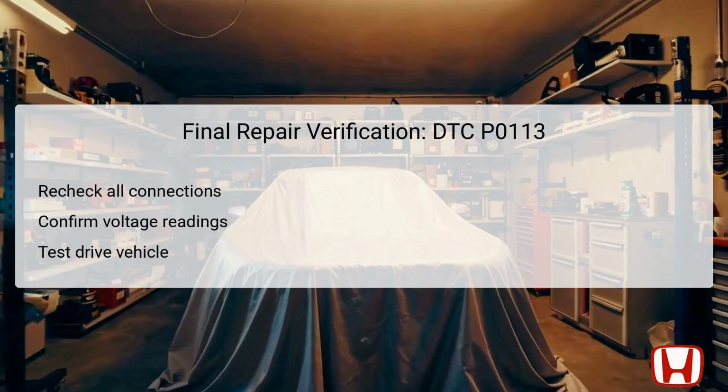After completing the troubleshooting steps for DTC P0113, it is essential to conduct a final verification process to ensure successful repairs. Begin by rechecking all connections made during diagnostics to confirm that they are secure and properly seated, as loose connections are a common cause of false readings. Next, utilize the HDS to confirm that the voltage readings from the IAT sensor are within the normal range.